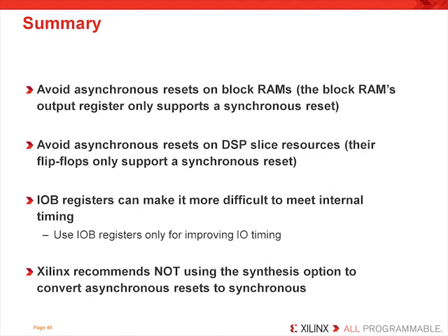Note the use of IOB registers can make it more difficult to meet internal timing. So use the IOB registers when you're trying to improve your I/O timing. That's the clock to output time or your setup time on those input or output registers. Xilinx recommends not using synthesis options to convert asynchronous resets to synchronous resets. And we discussed that in a little bit of detail, and probably at this point you're not going to ever forget to do that.